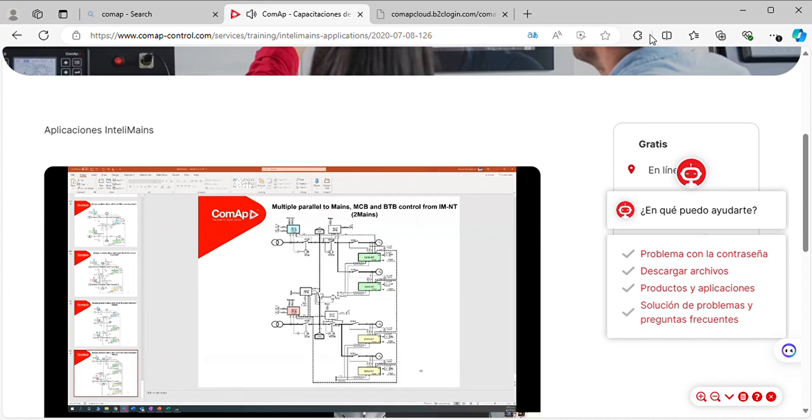Similarly, on the bottom half, if I fail the utility, open up the MCB, and I would manually go and start the generators. So the gensets would start up. It will go to the nominal RPM. Once they are ready, I can synchronize, but they are independently working. So this is my top half, this is my second half.